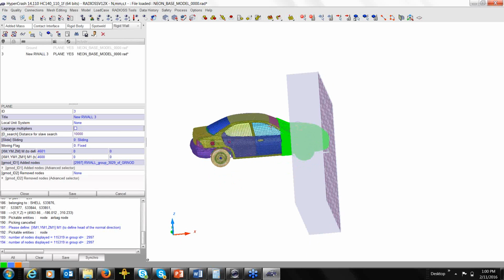Yeah. Now, but you don't want to move your wall too far also. Because if you move the wall far, the vehicle has to travel that distance, that space you create between the wall and the vehicle. It has to take time to run to that level until it touches the wall. So you don't want to move your wall too far. But what we have by experience for a full front impact or end cap, we set the wall maybe about 2-3 meters away from the vehicle. So at that level, otherwise you see your curve.